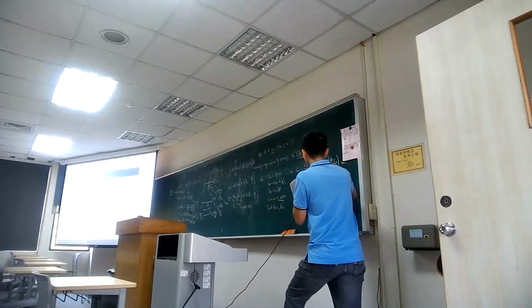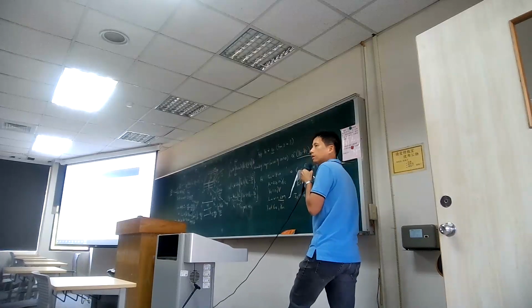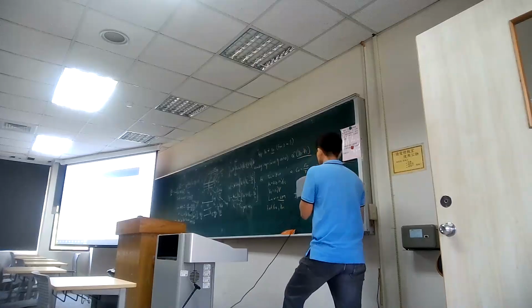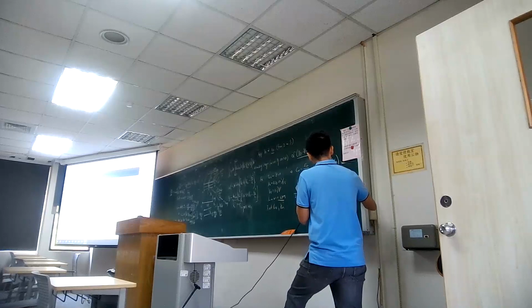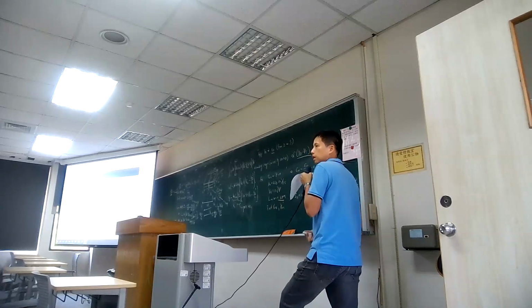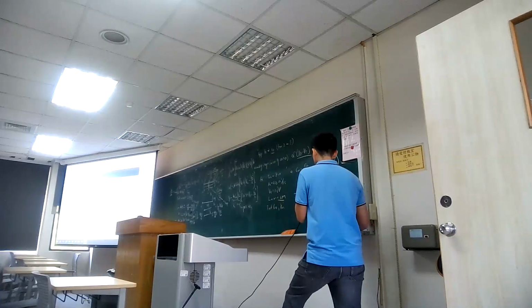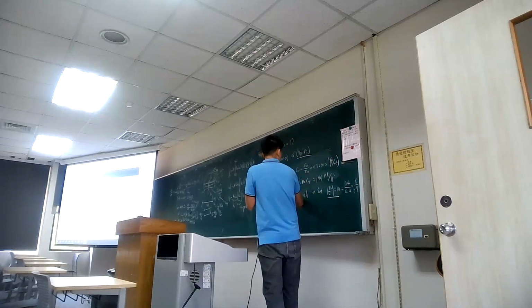So for instance, if you are working with 10, that means your critical dimension of the width over length could be 4 micrometer over 0.4. That is the minimal one. But sometimes you want to avoid any charge implication, like when you have a certain variation, so people also may enlarge your dimension to 8 over 0.8. So you can try to play with the dimensions, and other than the constants, you can play with this. So you can put everything in, and we assume it is the saturation region.